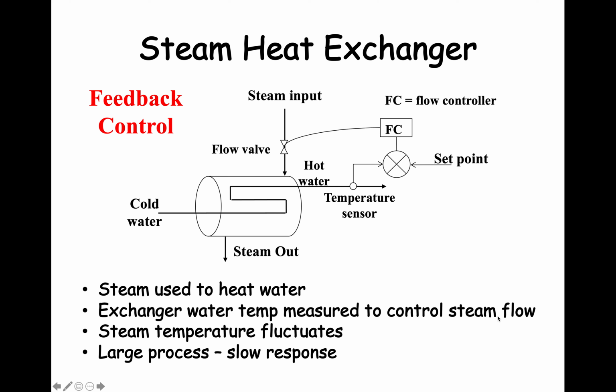The problem is that the steam temperature fluctuates, which means that the amount of heat input can fluctuate even if the steam flow rate is kept constant. And if the amount of heat input fluctuates, the hot water temperature leaving will fluctuate.